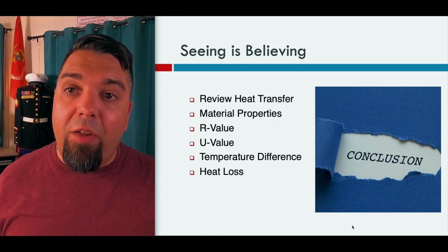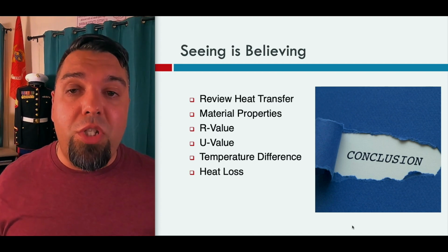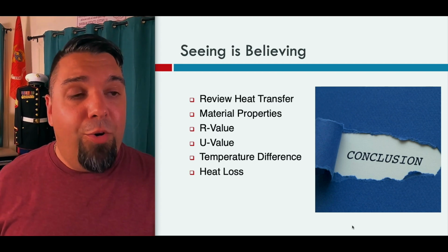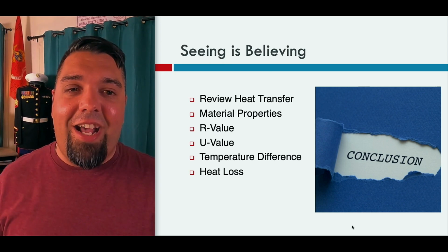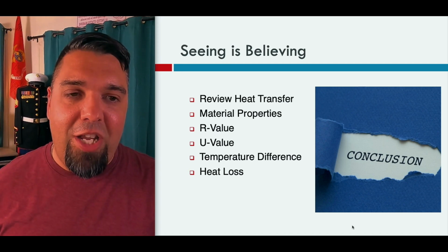Don't forget about infiltration. This is why we don't do it longhand, right? And why we use software to bring that piece into it, what the air changes per hour are, or you better take a really good educated guess based on the size of the home and the age of the home as to how much air is going to be changing over in that space.